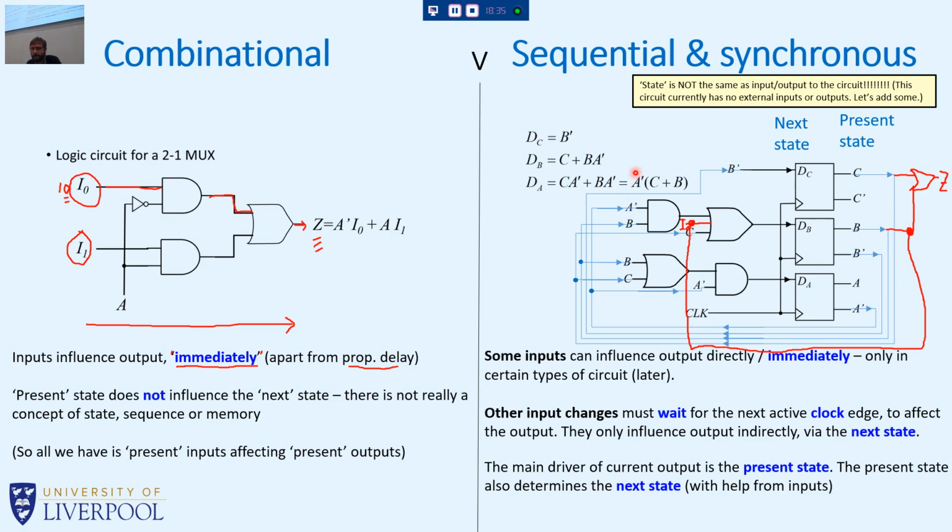So if the output of DB is low and I0 is high, what happens to the input of? So when you say the output of DB, do you mean really this state here? So this present state of flip-flop B is high and I0 is low. Well, because we've got an OR gate here. I've not drawn that very well, actually, because I've just connected them both to the same line. I've just realized in my rush. So I can see your confusion.